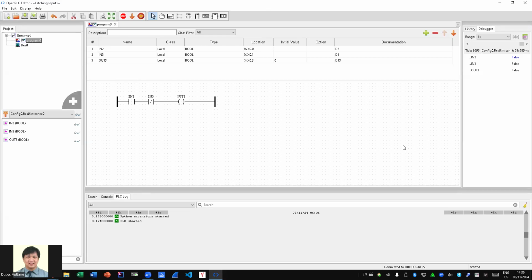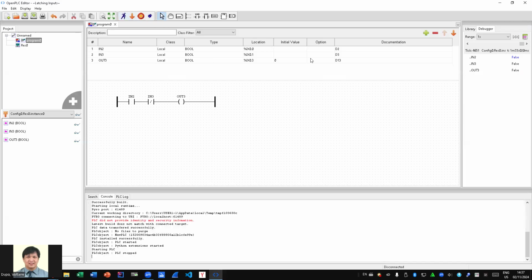If it is a push button switch, it is momentarily closed once you push it down. Once you release the switch, it goes back to an open condition, and we all know that an open condition kills the output. What if you want the input to have a value which is specifically set? Once you push the push button down and you release it, the output should still be on unless you press the start or change the false condition of in3, the stop button in this case. This is the conundrum that we're in.